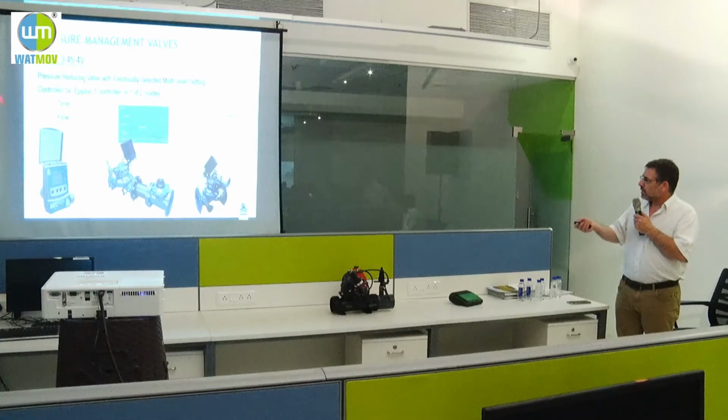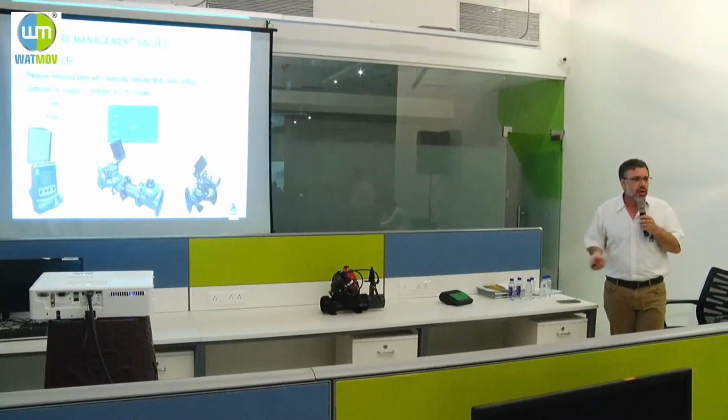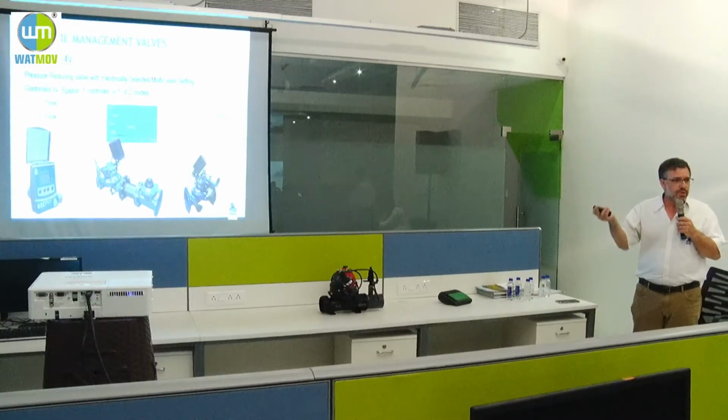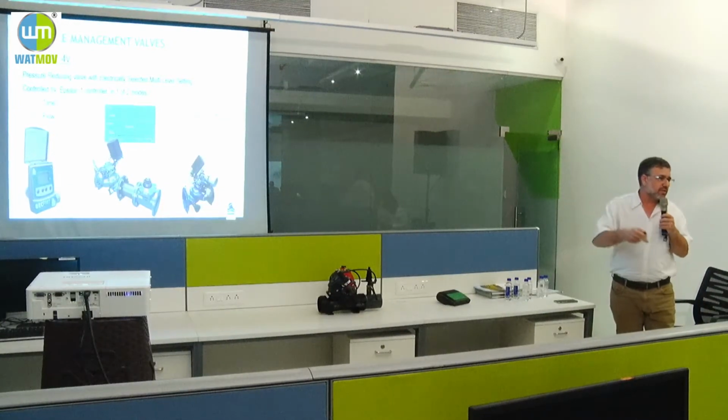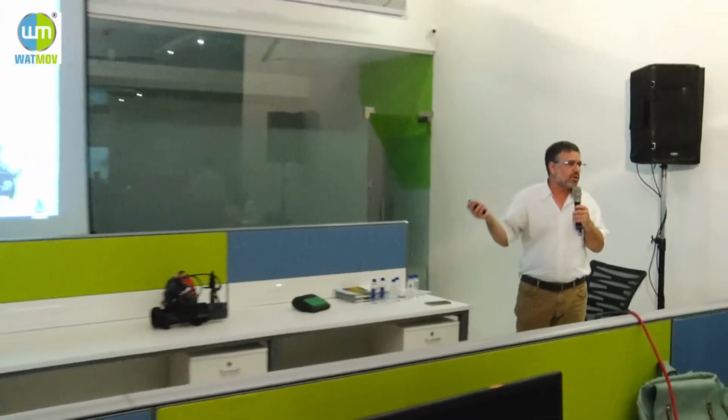So this unit, the Epsilon, is also connected to the ports and reads the pressure all the time. And we will show you in a minute, in our cloud, it's not only changing the setting point according to day and night, it also provides a lot of information about what is going on with the valve. What is the inlet pressure, the outlet pressure, what is the flow rate, of course the quantities, and when the changes are made. So you get full information about the operation of this area, and then you can make a decision. Once again, at this stage, you make the decision by yourself.